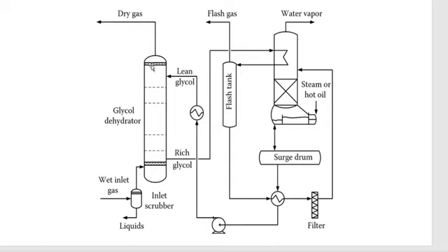Here, another mist extractor catches any small drops of glycol that come with the dry gas. Okay. This dry gas must meet the specification of the gas we request. If not, we test it and bypass it, returning to the tower.